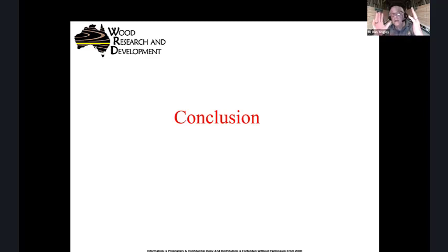Just stop the verticals. If you've got log girders, stop putting them on the seats at the abutments or the piers with vertical bolts that go straight down through the center of the girder. It doesn't work. It's proven it doesn't work. It's got decay in it. That's why they have fire problems.